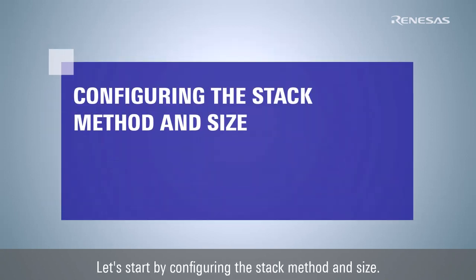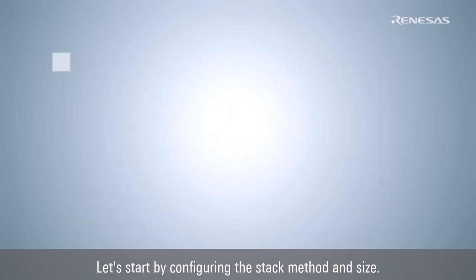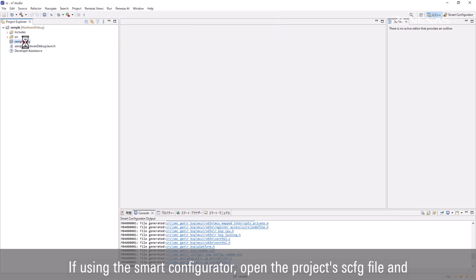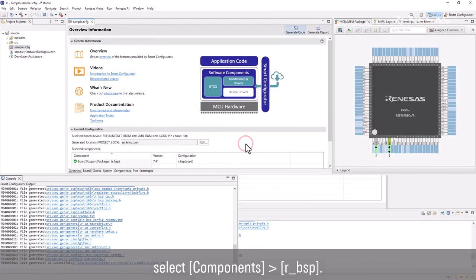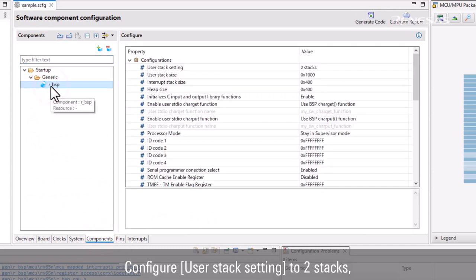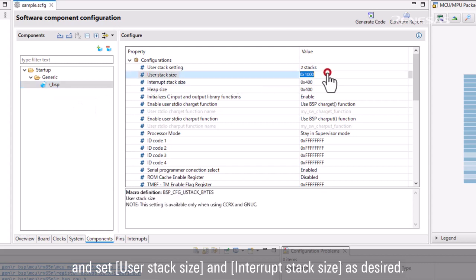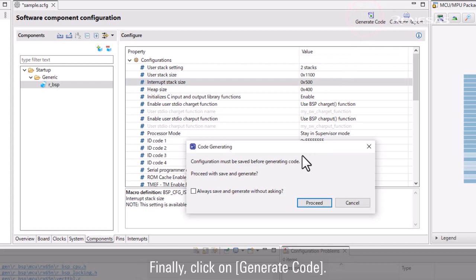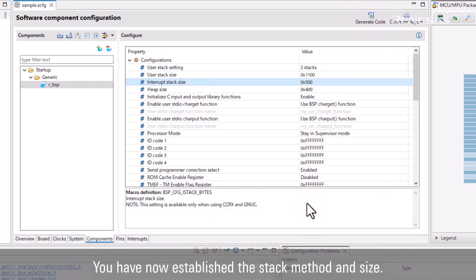Let's start by configuring the stack method and size. If using the Smart Configurator, open the project's SCFG file and select Components, RBSP. Configure user stack setting to 2 stacks, and set user stack size and interrupt stack size as desired. Ensure the number is a multiple of 4. Finally, click on Generate Code. You have now established the stack method and size.